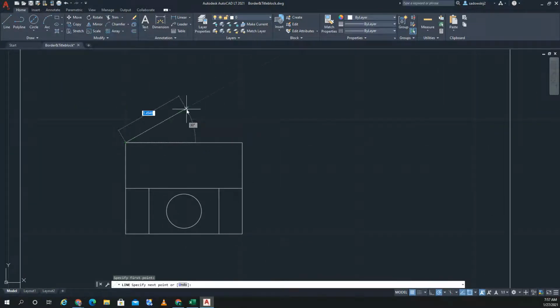All CAD systems, as you guys have noticed, you can see the length of the line moves as I use the rubber band effect and stretch this around that blue and white box. The gray one, the angle changes too. Well, how can I lock it into a certain angle? You can. I just stretch this line over a little bit longer than it needs to be. You hit the tab button, tab toggles back and forth in between. And I want this to be 47.